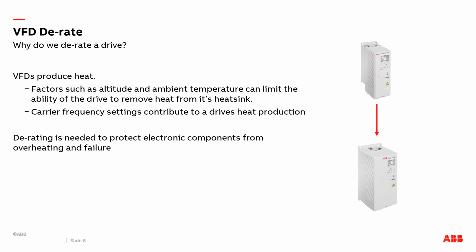There are factors, though, such as altitude and ambient temperature, that can limit the ability of the drive to remove heat from its heatsink. Another factor on how the drive produces heat is carrier frequency, which relates to the output of the drive. That carrier frequency can also increase the drive's heat production. When we're looking at derating, the main goal is that we want to protect all those electronic components from overheating and failure.